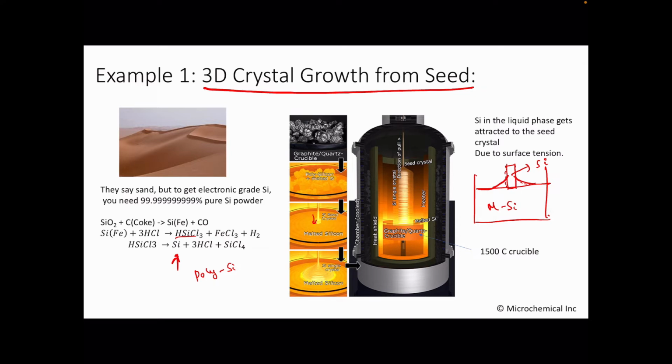And as you see, the temperature here will be much smaller than the temperature here, and the silicon at these regions will start to melt, and then it will start to crystallize. If you are able to do it very slowly and if the temperature is well controlled, you will get a solid silicon ingot, right? The temperature here I have written as 1500. It is typically 1650 C or such. It of course depends upon the pressure in which you are operating, right? So this is the basic of growth using the Czochralski process.